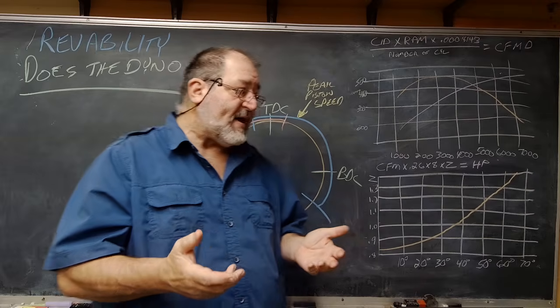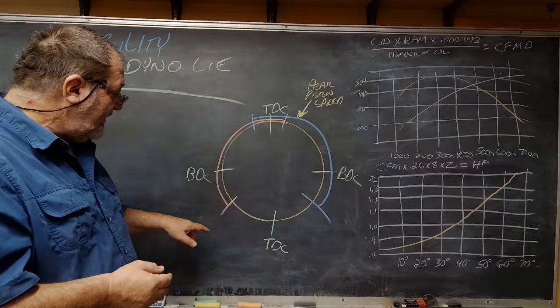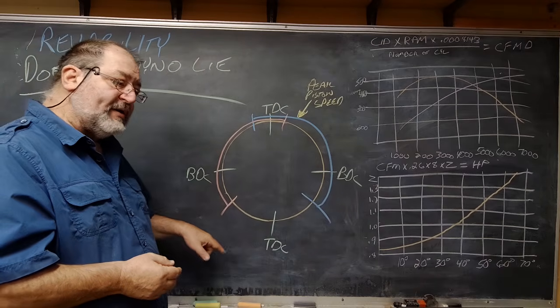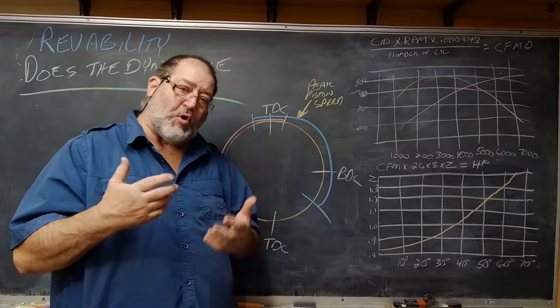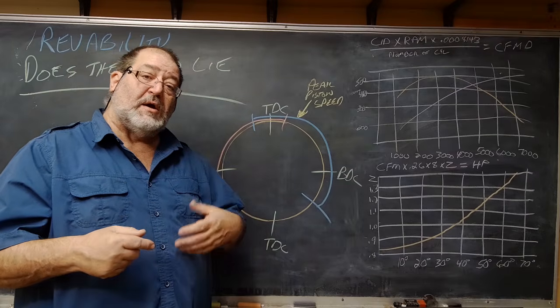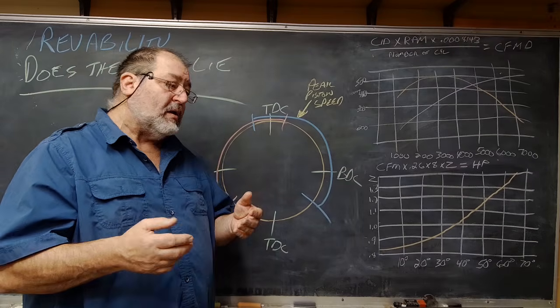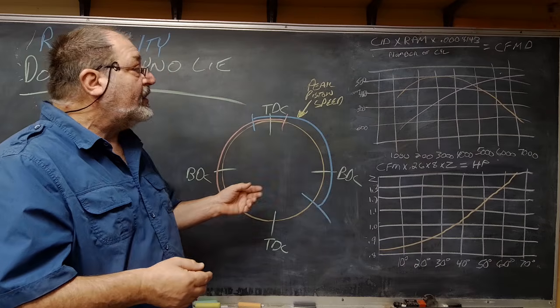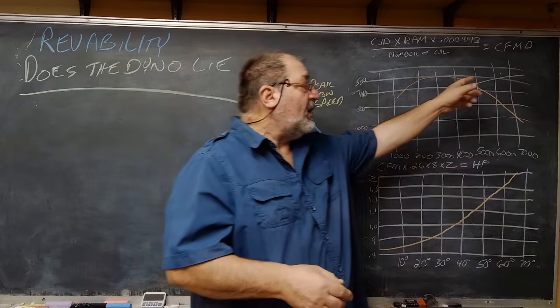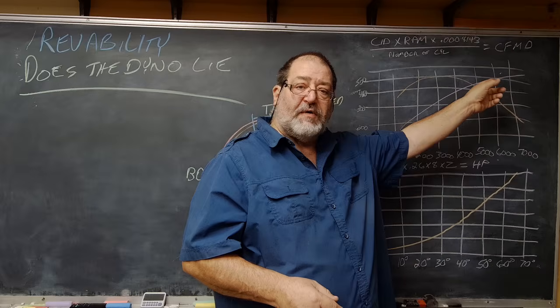Now, that's why a lot of times I'm pushing that exhaust opening point. I'm trying to get that blowdown to happen to free up that power. That mostly will show up on a dyno as carryover.